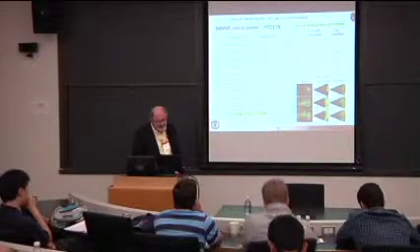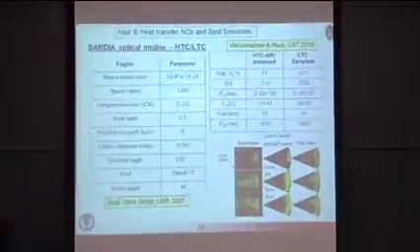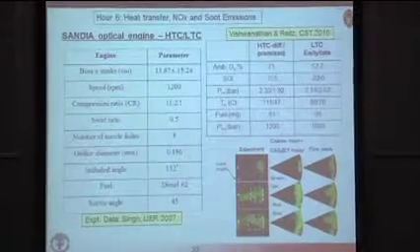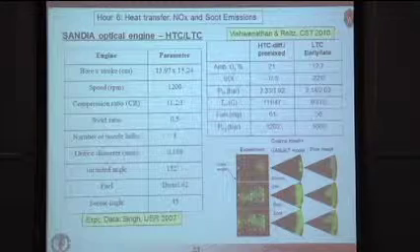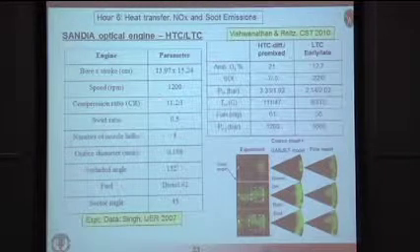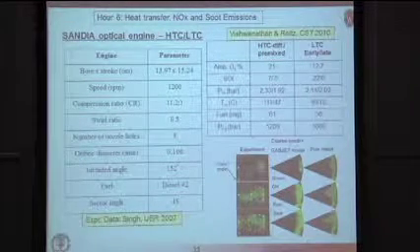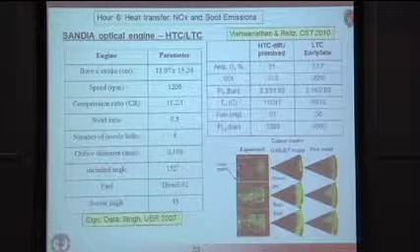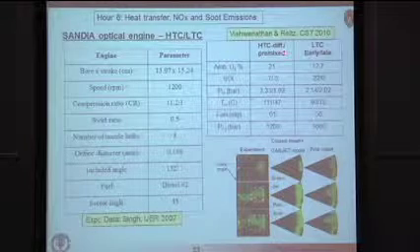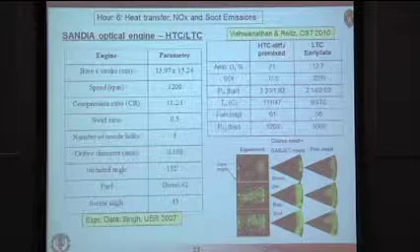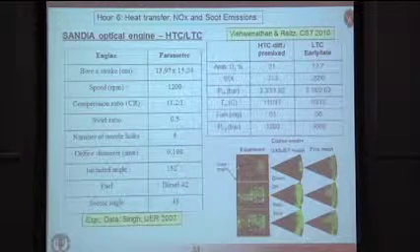We've also done some simulations with the soot model of the Sandia optical engine. Again, this is in Mark Musculus's lab, where he has made extensive measurements of soot using LII and other techniques. Some description of the engine here. It's a heavy-duty Cummins single-cylinder optical engine. He's operated this engine over a wide variety of operating conditions, including high-temperature combustion with diffusion combustion or premixed combustion, and then also low-temperature combustion with early injections or late injections.